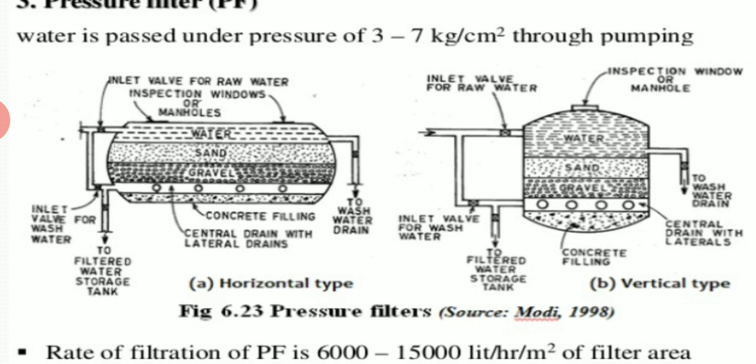The diameter of vertical varies from 2 to 2.5 meters and length varies from 2.5 to 8 meters. The filter is operated similarly to a gravity type of rapid sand filter, except that the coagulant water is usually applied directly to the filter without mixing, flocculation, or conditioning.